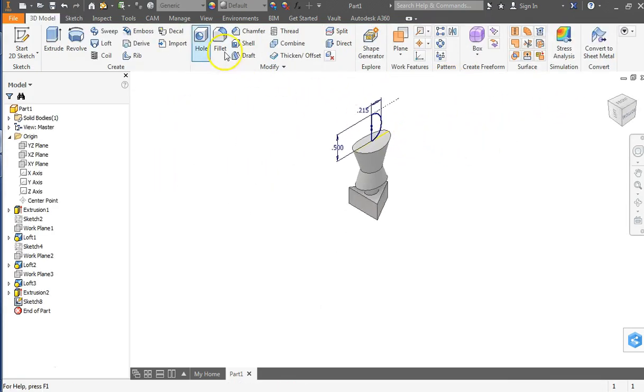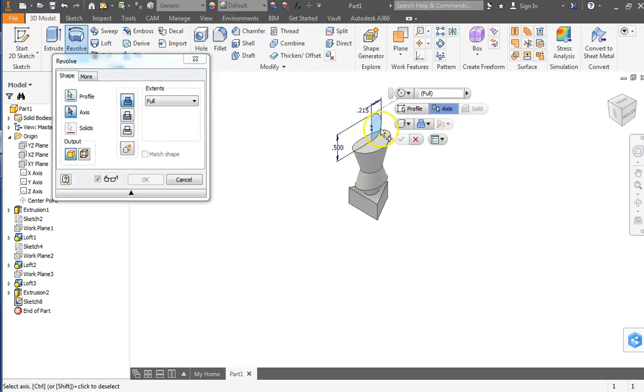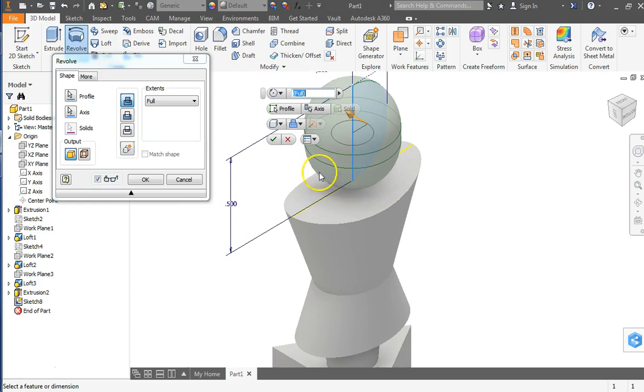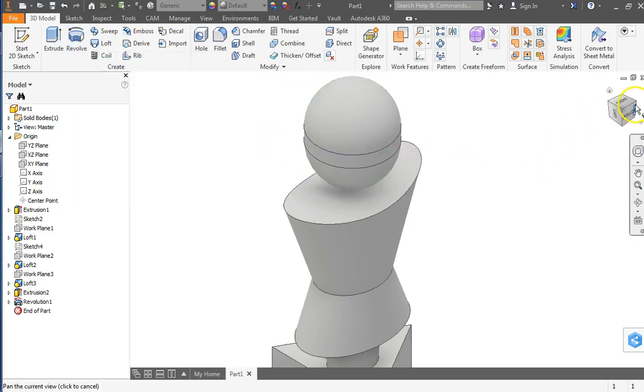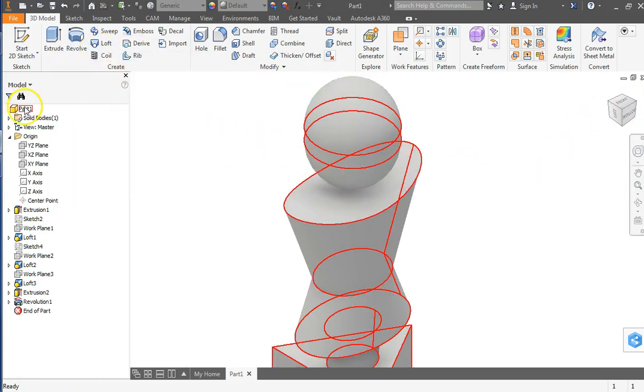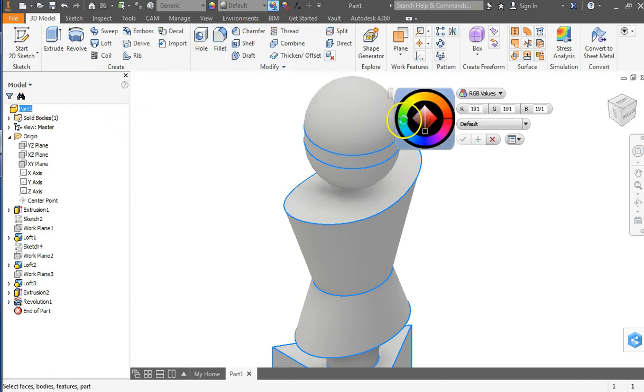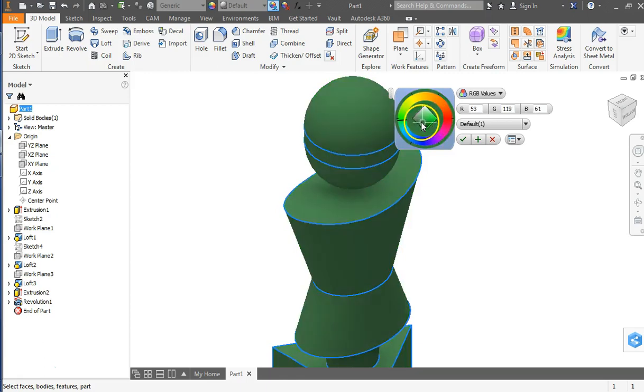And we're going to use the revolve tool. So only one profile auto selected. I just now need to choose the axis. I think that's already selected. Revolves. I'm going to choose accept. And I can color my parts. I'm going to grab the whole part name here. I'll grab a green. You can play around with the shading of the green if you want.